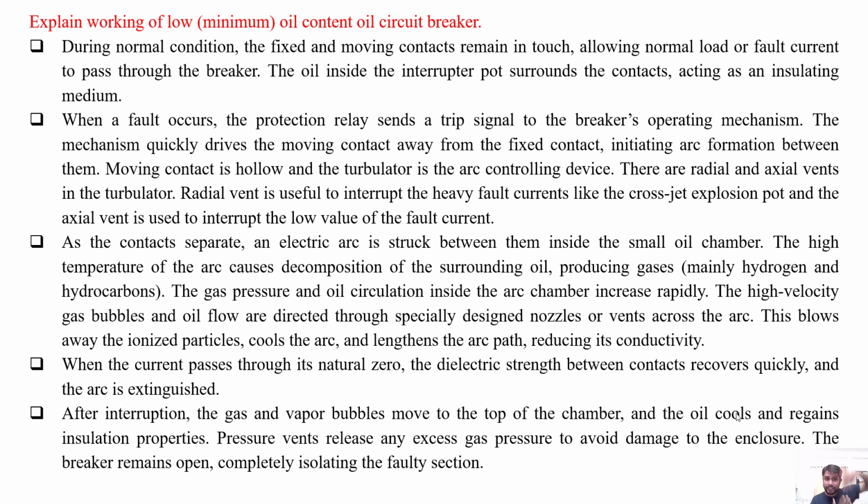Now, as the contacts separate, an electric arc is struck between them inside the small oil chamber. The high temperature of the arc causes decomposition of the surrounding oil and produces gas, mainly hydrogen and hydrocarbon gases. The gas pressure and oil circulation inside the arc chamber increase rapidly.